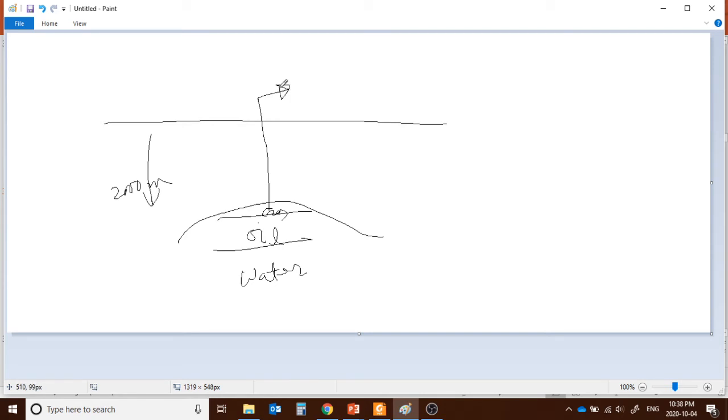Now if you take out the crude oil from here, and you don't know which phase it is, then when you try to take it out, it could expand, or the amount you find could be much lower. Why? Because gas is dissolved in this oil. So for instance, you imagined you'll get 200 barrels, but because it's at higher pressure, 2000 psi for instance, when you take it out to normal pressure, it could be something like 180 barrels.